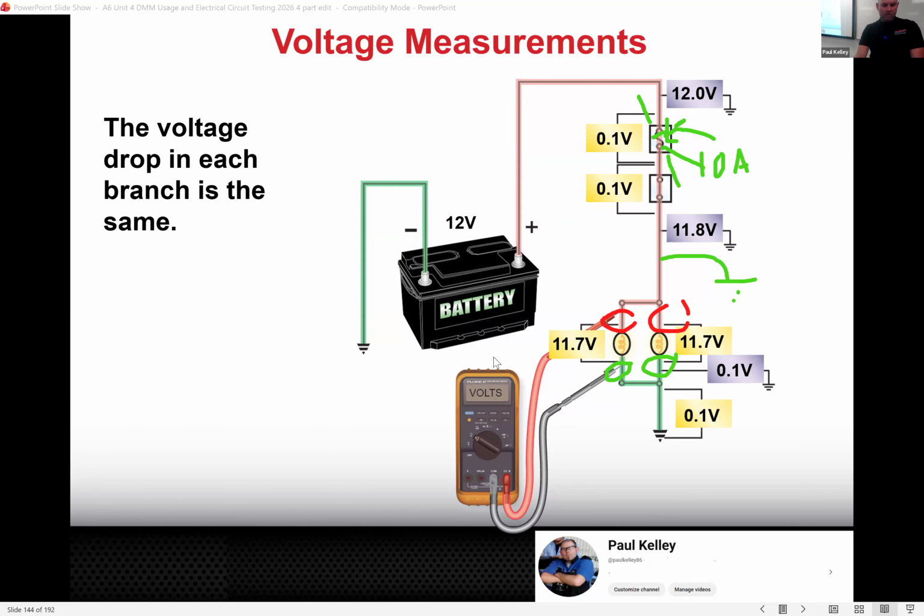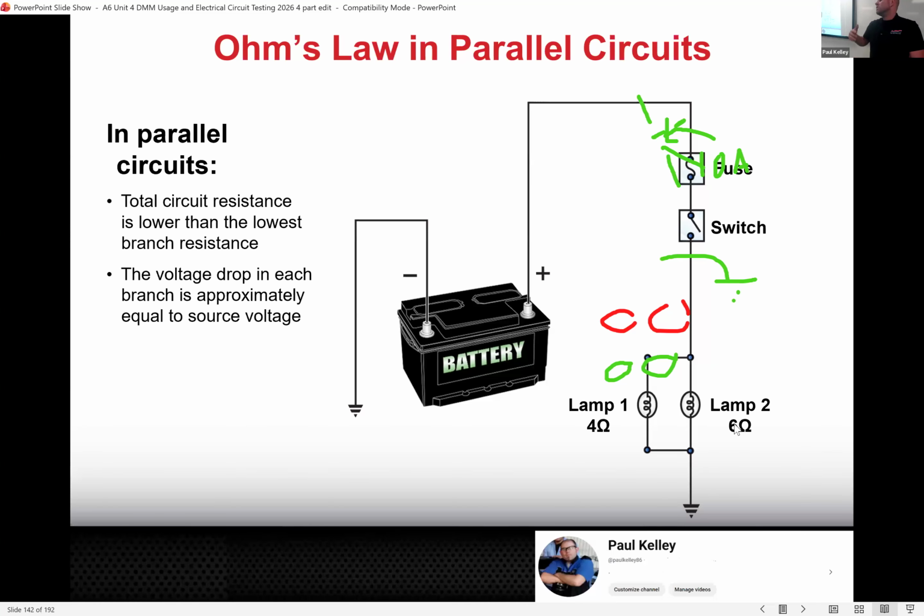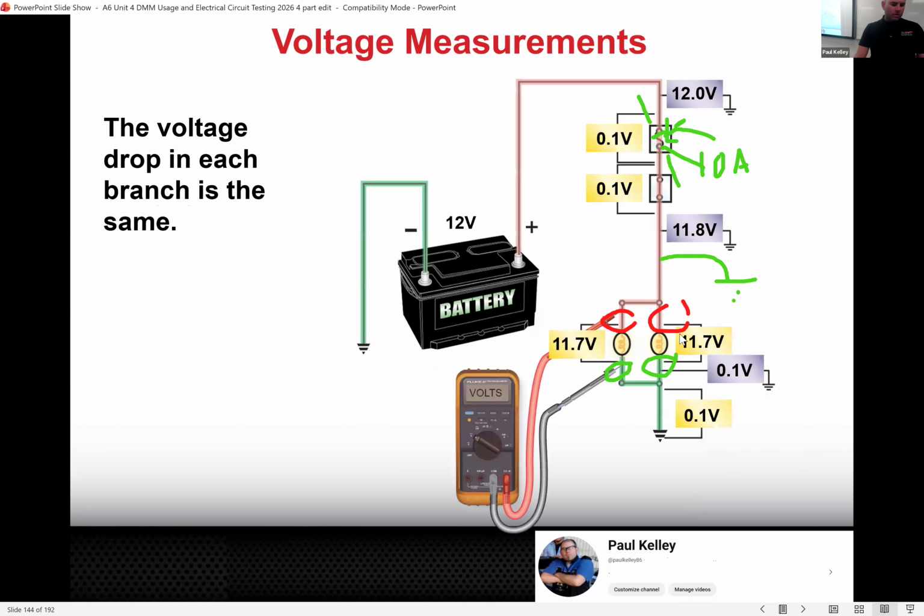Like I could even back up. We had some numbers. Exactly. And if I measure OL and OL, didn't I just double check myself that, yeah, these bulbs are definitely bad? So once in a while, I'll throw resistance in just to double check myself. Some of the more practical times you might measure resistance is maybe with an engine coolant temperature sensor. There are times, but typically with electricity, the voltage drop and the available voltage combined are going to tell you everything. You could even calculate the ohms using the voltage and the amperage anyway. So the voltage just tells you a lot.